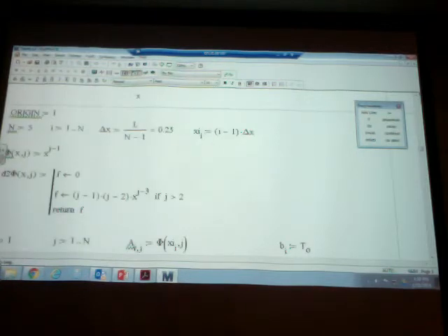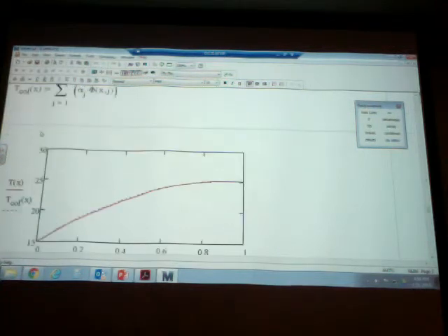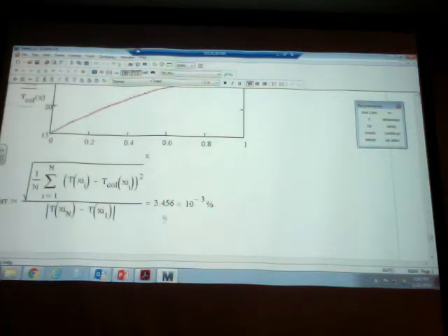If I use 4 points, let's use 3 points. One at the beginning, one in the center, one at the end. That's the minimum you can do, right? So we're basically approximating the solution with a parabola. If you use 3 points, the trial functions are going to be 1, x, and x squared. So you're basically approximating the sines and cosines with a parabola. How well do we do? Well, now we start noticing some deviations, but it's still very, very close. And if I update this, now I'm at 0.4%, which is still acceptable numerically, but you can see how good the solution can get.